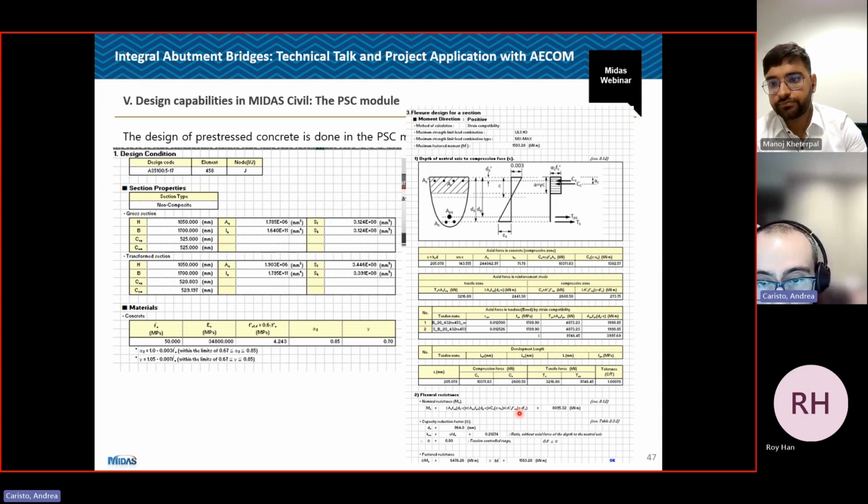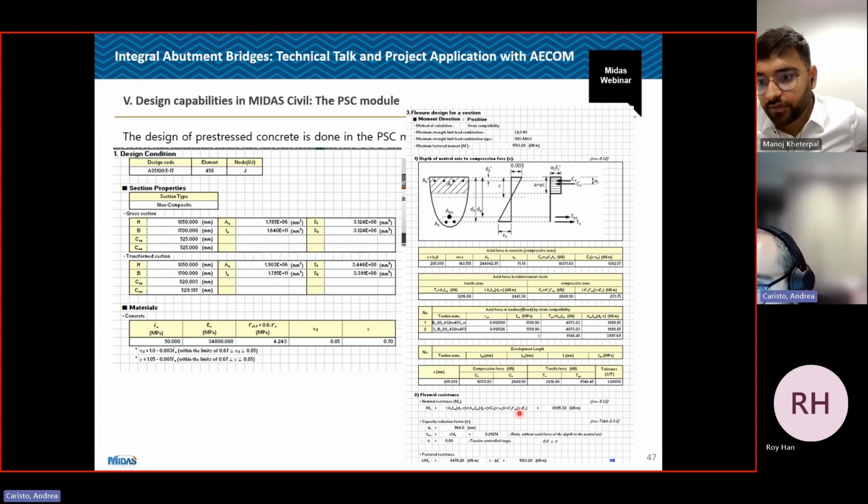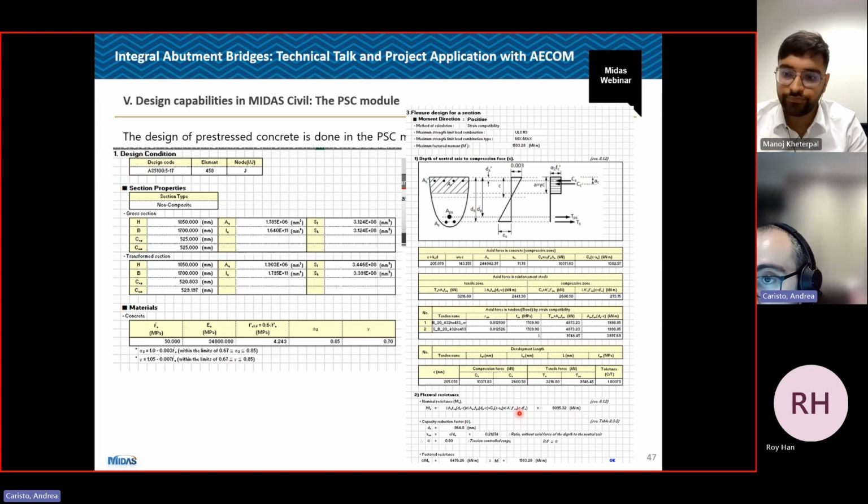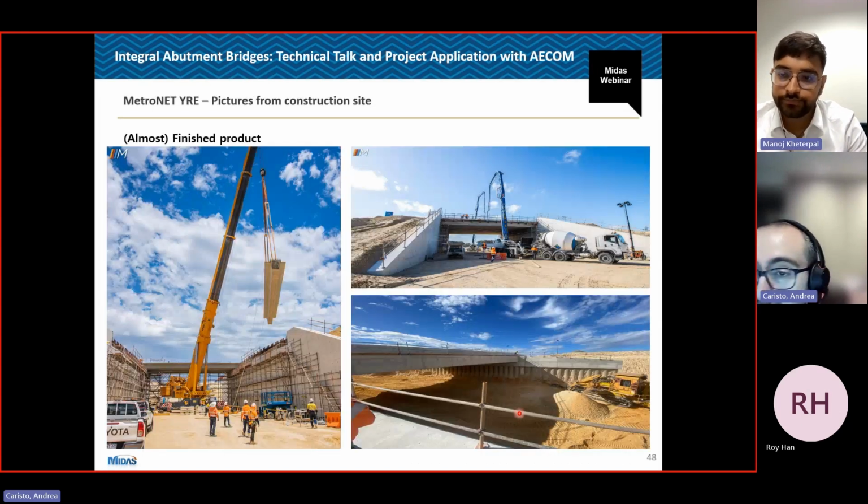It will be the tensile stress in your beams. Maximum compressive stresses as well. You don't want to exceed those. You have flexural checks, and obviously cracking checks. This is what normally drives your design in these beams.